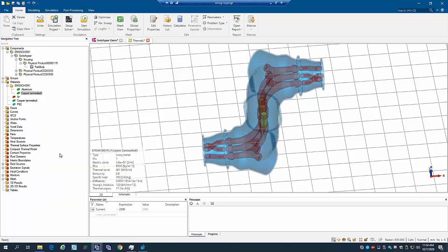All the other properties, thermal conductivity, density, and thermal capacity, the 3 numbers are pretty much all set if you use the library material. Now, this is a switchgear. If you're working in this area, you may know this one was actually sealed and filled with pressurized SF6 gas. It's not like your normal air because that's too easy to cause breakdowns. So what you can do is assign the internal of this device to have a different gas than the background gas. Let me show you how that works.